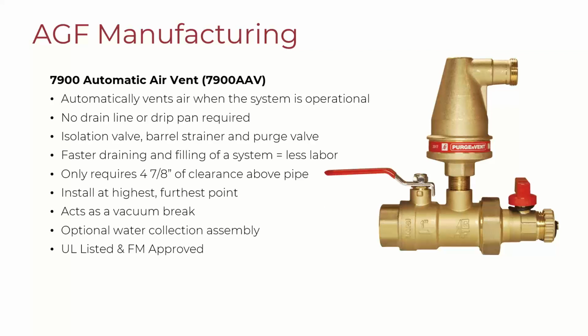Again, knowing that if you have a strainer, NFPA 25 requires that you clean and flush your strainer, we figured it'd be most convenient for all involved if we automatically put a flush valve with a garden hose cap and chain clean out so they could do that. Acts as a great location to do the initial air purge on the system or to be a vacuum breaker for your large system. So this singular bottom valve, then the center line of it, feeds up into our automatic air vent.